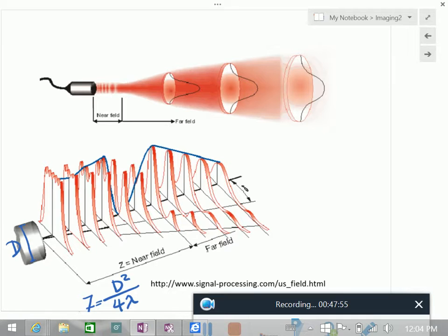But if you remember when Giancarlo wanted to test, when I saw the very small specimen, I told you we can't use these big 100 kilohertz transducers. This is exactly for that reason. Because whatever you measure, if it was only 1 inch thick, right? Yes, 1 inch. Those 100 kilohertz transducers are really large. At that time I didn't explain it to you, but this is what I was thinking about.